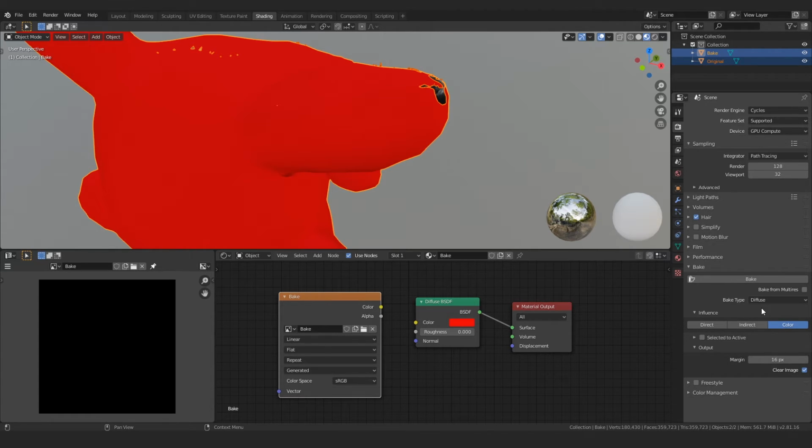So technically in 3D, a diffuse map actually takes into consideration the color data and the lighting or shading of that color data. There's another map type called an albedo map, which literally takes into consideration just the color data without any shading. The shading in that situation with an albedo map is generally dictated by another map called an ambient occlusion map.